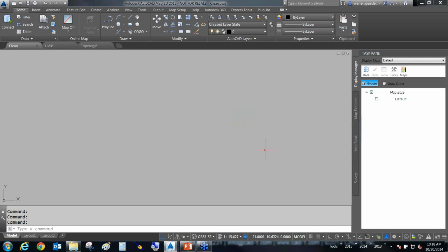Okay, so what was the question real quick before I move on? The question was, hopefully you can clarify connection to SDE. It is not clear if one can connect to 64-bit, and Esri 10.1 has changed their dialogues, so what AutoCAD asks is not the same as what Esri calls it in their dialogues. Okay, quick answer, because I'm not going to get into the SDE portion of it that much, but we can connect to all sorts of data, like I was mentioning, the GIS data. Quick answer, yes, you can connect to SDE. The trick to connecting to SDE is that you need the 64-bit DLLs.